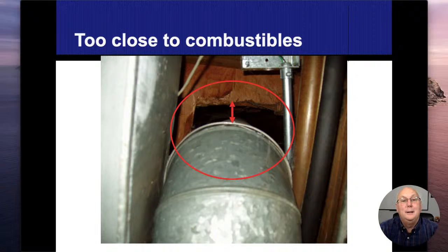All right. In this case, it's actually touching the wood. Now, granted, there were no burn marks or anything else on there, but it was still touching the wood, which is going to be somewhat of an issue. Even with this insulation on the pipes or the refrigerant lines that come to the vent connectors.